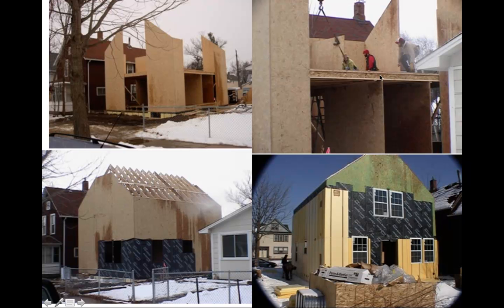So in a sense, this flooring system ends up serving two functions. In addition to supporting the load up above, it also is the buckling support for this, so that the height of this column is actually much less. Now, one wonders, okay, so why did we build a house like this, or why was this house built? One of the reasons for that is looking at a different type of basically weather protection and insulation system.